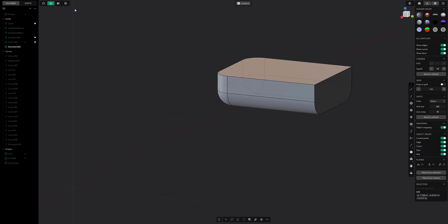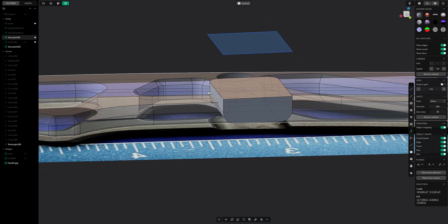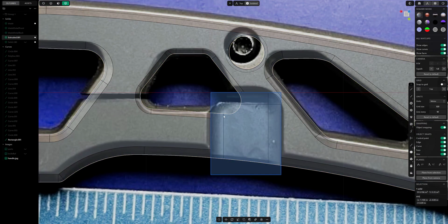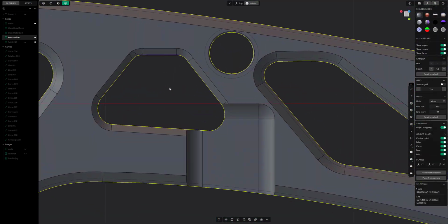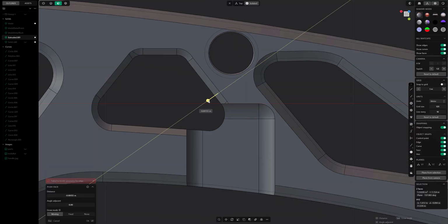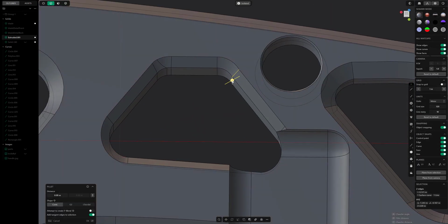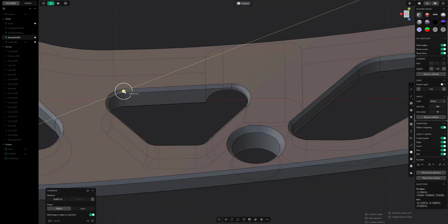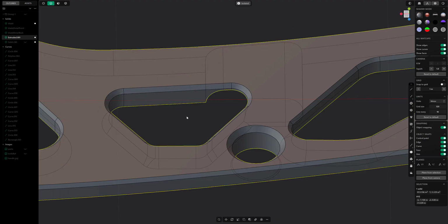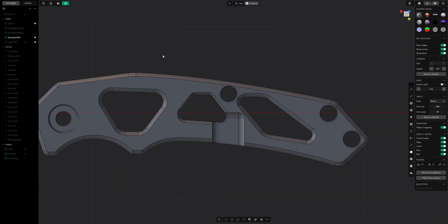Here I'm just going to have a simple cube, fillet the edge, and then we're going to boolean it out, and you can see it makes that nice kind of divot there. And we can go ahead and I can see if I can try to adjust these, but again, these might fail because of the complexity of the face. And so here I'll just, again, use that same trick, just do one, then do the other. After doing that, you can see I lost that chamfer on the bottom, so I just go ahead and rechamfer it so it matches the others.